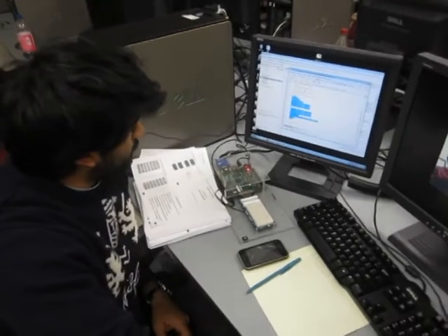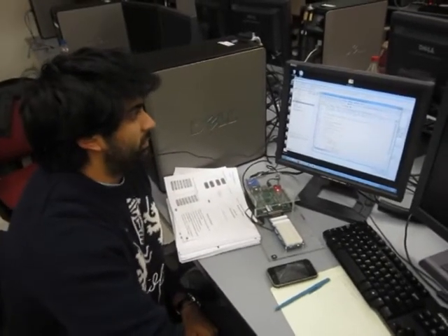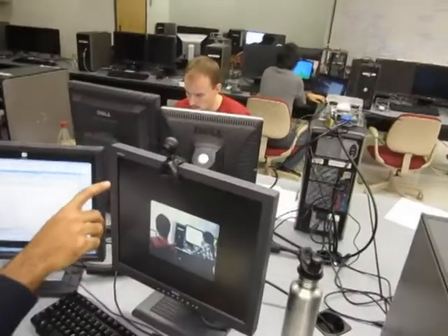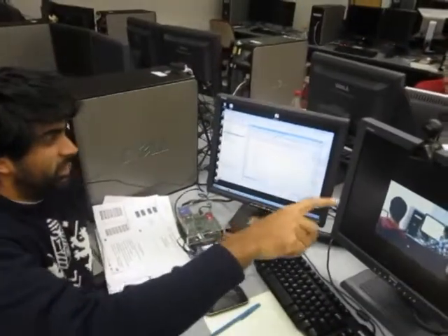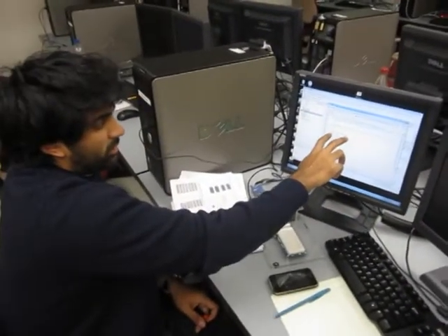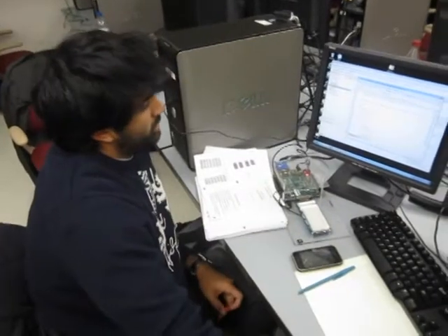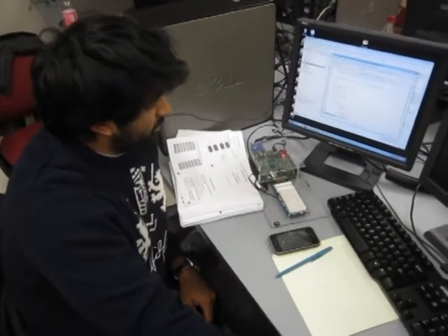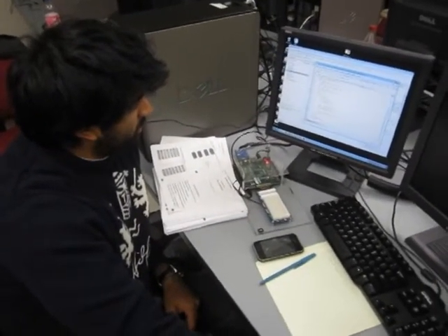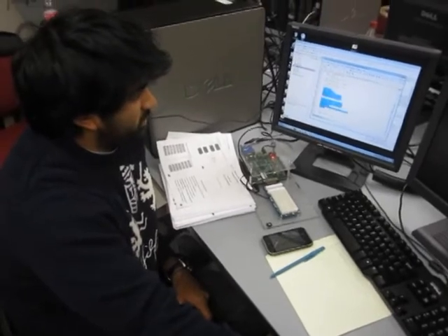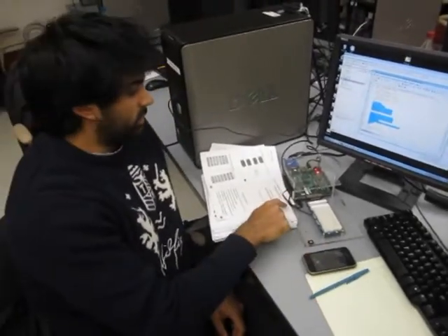The second script takes the 256 RGB video, gets the current snapshot of it, and downsizes the video into 8-bit color using simple bit shift operations. From there, we serialize the data and send it over UART to the FPGA board.